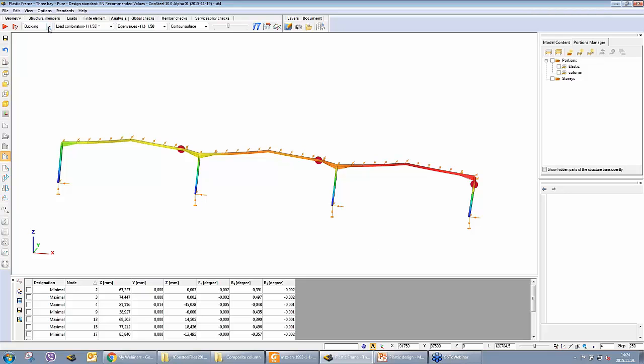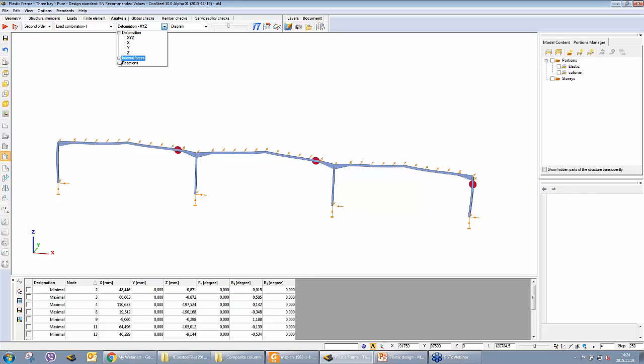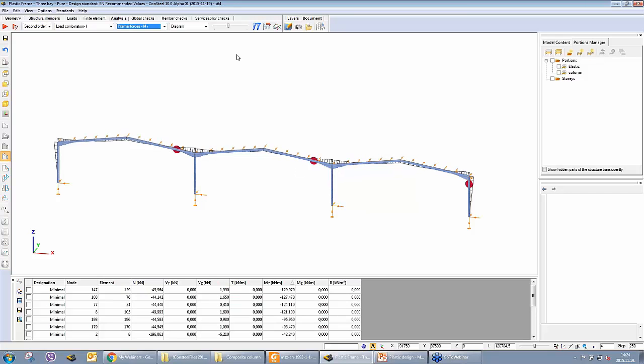And we can see also the second order results including these hinges. So we have now 3 hinges at the design load level, and it is of course taken into account when we see the bending moment or any kind of internal force calculation. So this part was about plastic hinge analysis in ConSteel briefly.